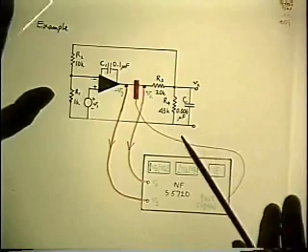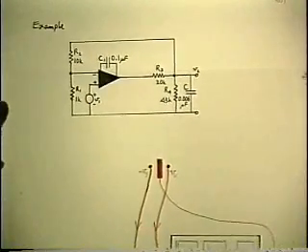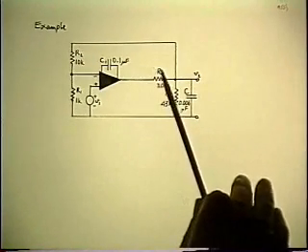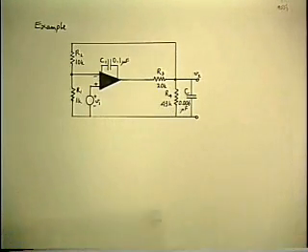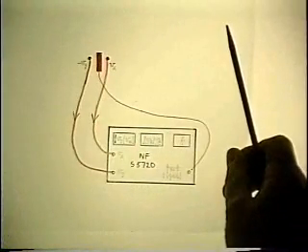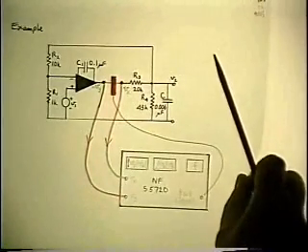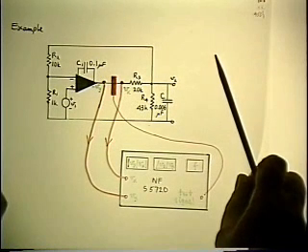And what you do in practice is you build your breadboard, closed loop, you turn on the power supply and it comes up and it runs, and you have this test instrumentation sitting on a cart somewhere, and your circuit is already up and running. All you do is wheel up your cart full of equipment and you hang on 3 probes while it's running. You don't even have to turn it off to do that.